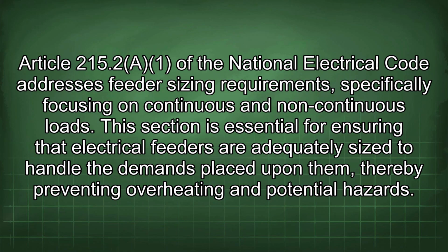Article 215.2a of the National Electrical Code addresses feeder sizing requirements, specifically focusing on continuous and non-continuous loads. This section is essential for ensuring that electrical feeders are adequately sized to handle the demands placed upon them, thereby preventing overheating and potential hazards.